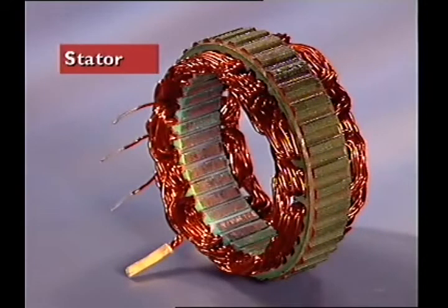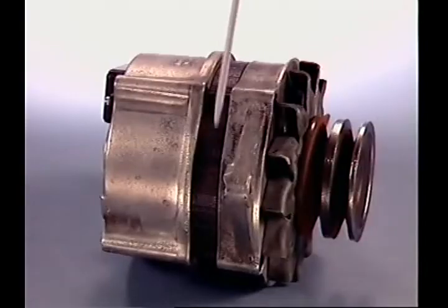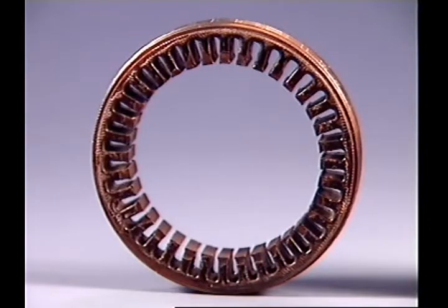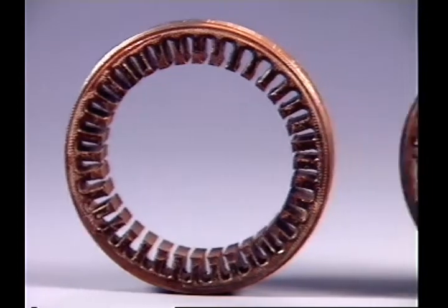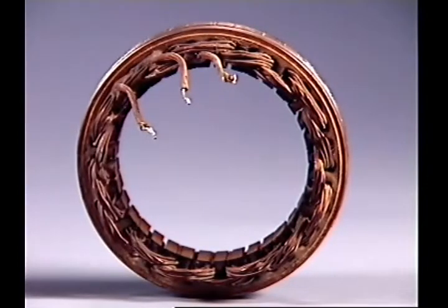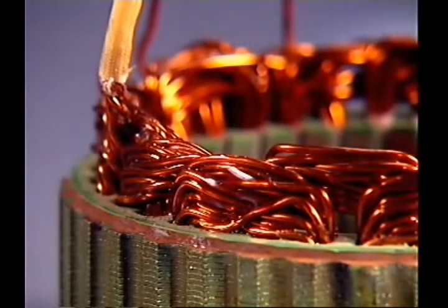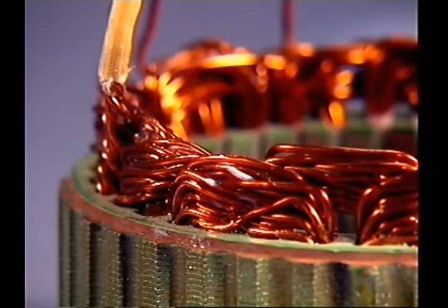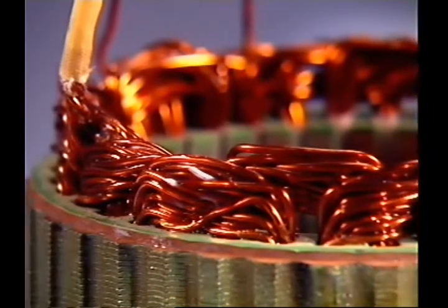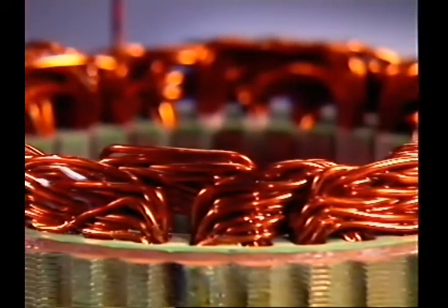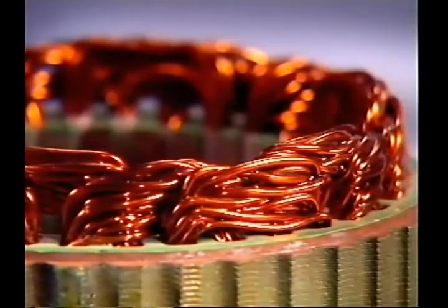This section examines the stator. The stator is mounted between the 2 end brackets. It consists of a cylindrical laminated iron core which carries the 3-phase windings in slots on the inside. The windings are insulated from each other and also from the iron core. They form a large number of conductor loops which are each subjected to the rotating magnetic field.